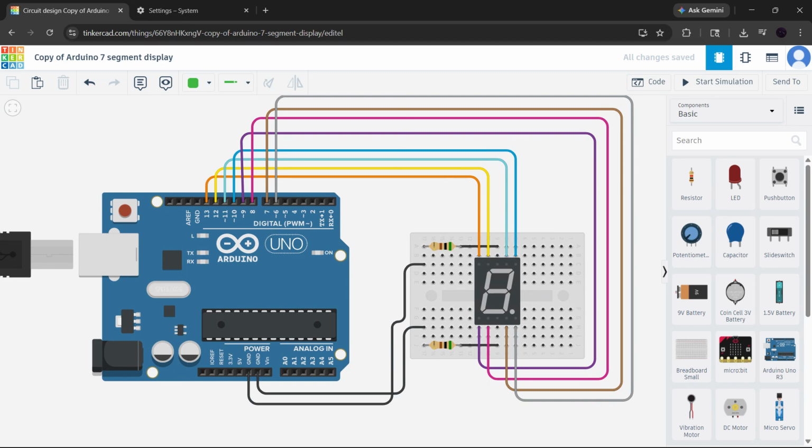A good practice is to run a basic sketch first, then slowly add more functionality until you find a line that triggers the error. The third thing to check is floating components. Sometimes a part looks connected, but the pin is not truly snapped into the breadboard. That can create a hidden wiring problem that causes the simulation to fail.